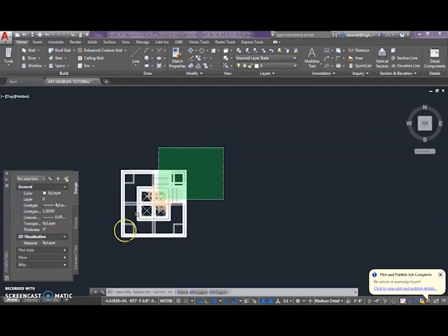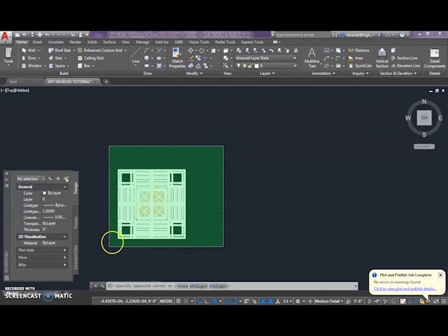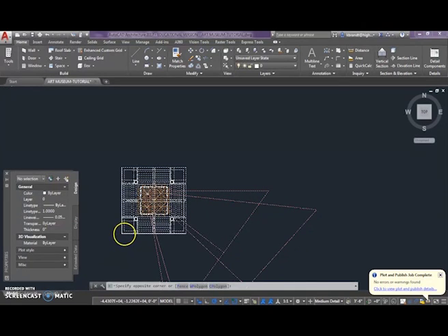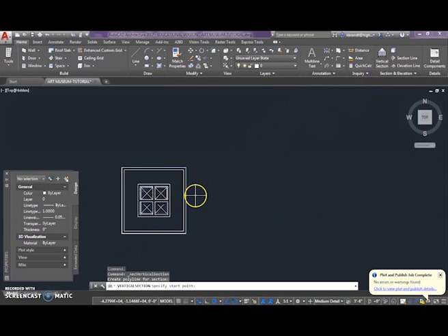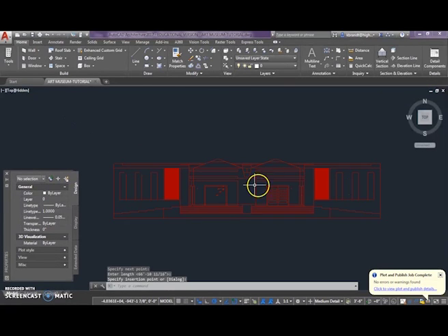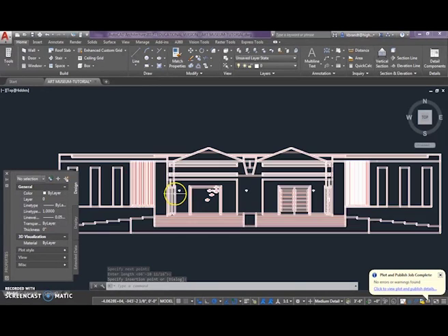To do this rendering, you need to start in CAD and you want to go to your top view. What you're going to do is go to your editing ribbon in the Home tab and go to the section and elevation panel. Click on the vertical section button and then it's going to prompt you to draw a line through your space and then you hit enter.